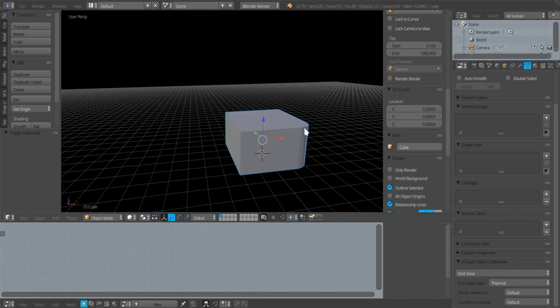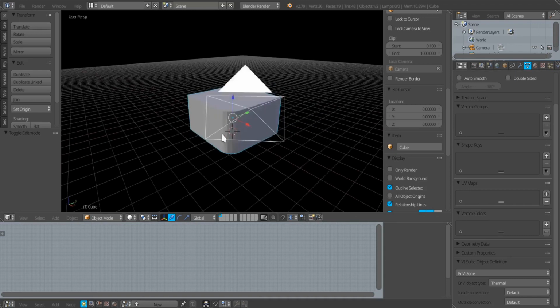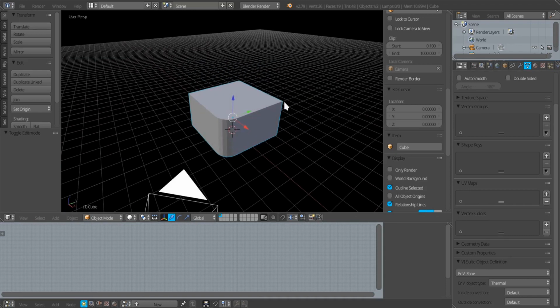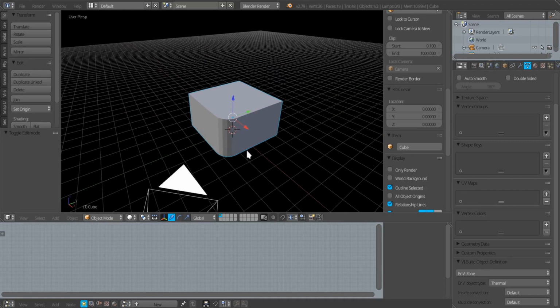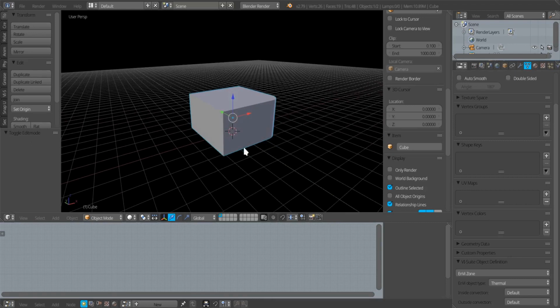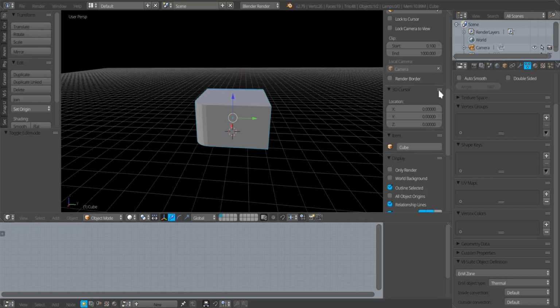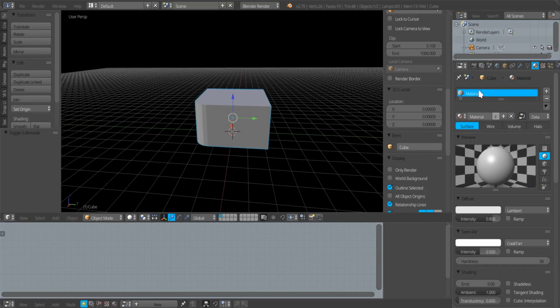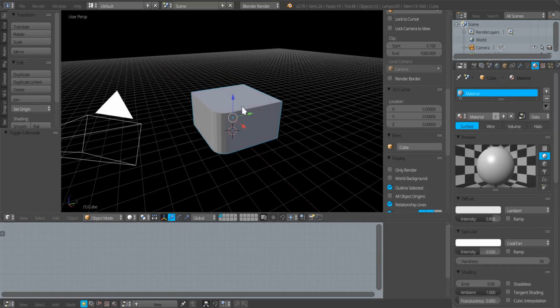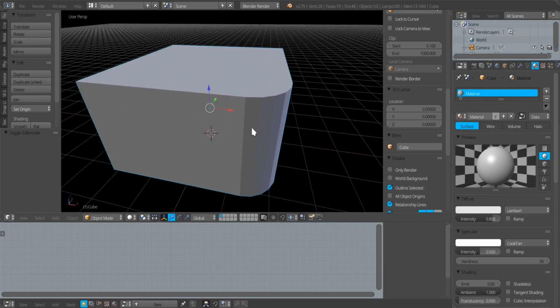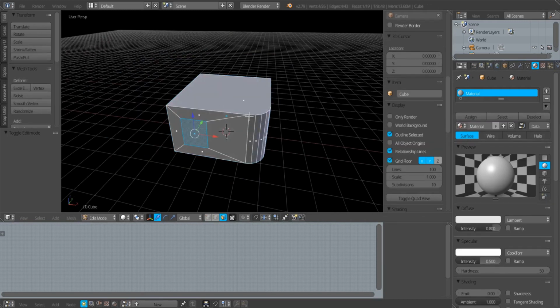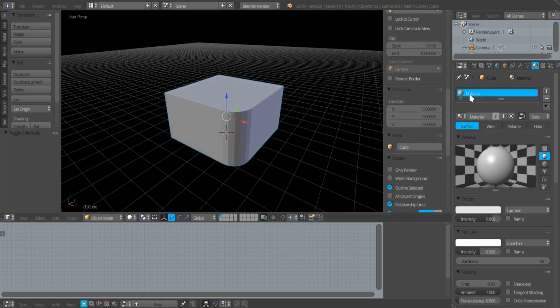So once I've set it to EnVi zone, the vSuite now knows that this object is going to be a thermal zone in EnergyPlus. But I do now need some construction characteristics to go along with these geometric faces. So if I come into my material tab, I'll see that because I've used a default cube, which has already got the default material associated with it, this material is now applied to all the faces. Even these new faces that I created, they've picked up this new material definition. So this existing material, I'm going to call it walls.